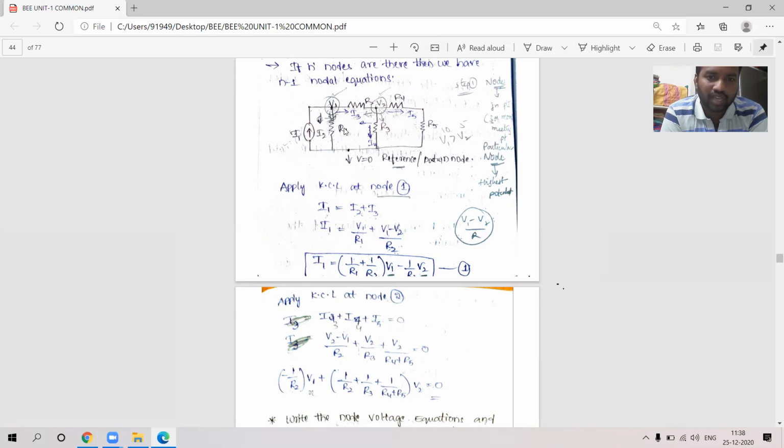That's why I2 is indicated downwards. In the circuit, I1 is an entering current, don't disturb that I1. I2 will be downwards. Similarly, for I3, because we don't know the value of V2, let us assume that V2 is lower potential compared to V1. So in step 1, the I3 direction will be from V1 to V2.